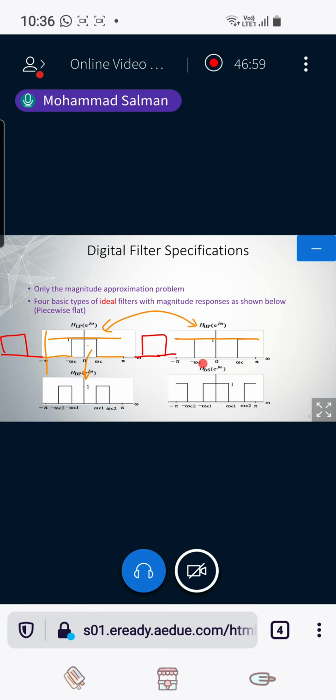And this filter is band stop, as we explained before. It's a complement of band pass. 1 minus band pass, you will get this one like this, right? Again, I design a low pass, shift, and take 1 minus to get band stop. Is this clear, ladies and gentlemen?